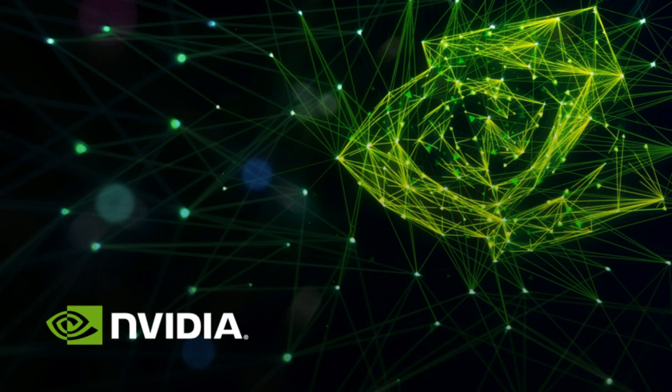Okay. Do I need a separate NVIDIA-enabled PC to develop for the Nano? And the answer is the Nano is the first Jetson that does not need really a whole separate PC for the whole flashing procedure. You do need some other type of PC to take an SD card and write the image to it, but it can be any laptop or desktop that runs Windows, Mac, or Linux and has an SD card reader on it.